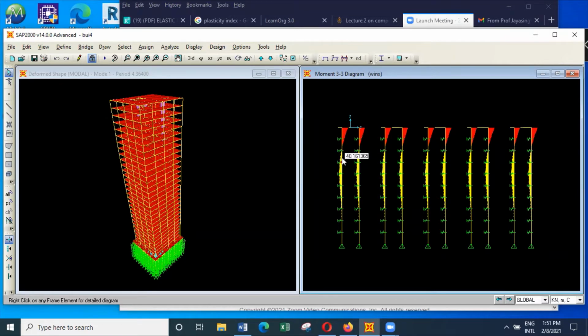So in the case of car parks, we have to allow for vehicular movement. And one of the requirements is road. If you're having road, the traffic moving in 2 directions, then you will find you need to have a passage that can allow the vehicle movement. And the width of the passage has to be about minimum of 7.3 meters.